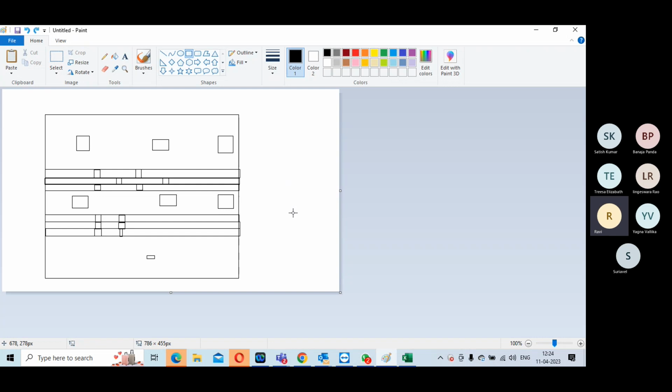AND isolation means only when power from both comes. Let's look at AND as a digital thing, right? AND means if both inputs are one, then only the output is one. But this was supposed to be a signal, right? That means what should be the other one? It should always be connected to tie high. So that if this input is 0, the output will go as 0. If this input is 1, the output will go as 1. But if you are using it like this, and this guy is shut off, then it goes to Z. So you have to understand that's the logic thing.